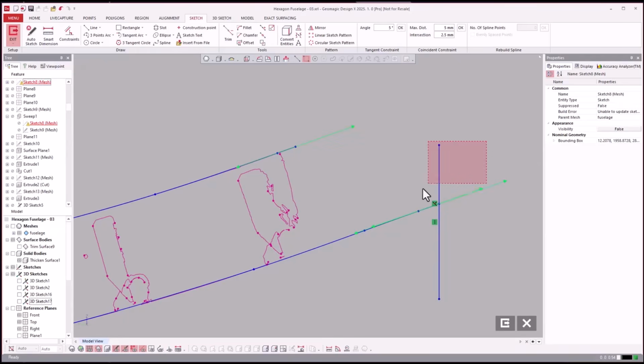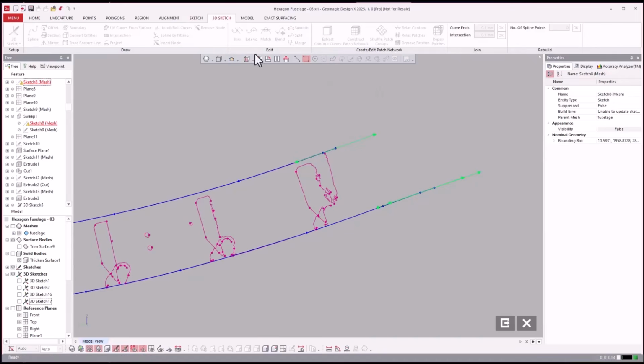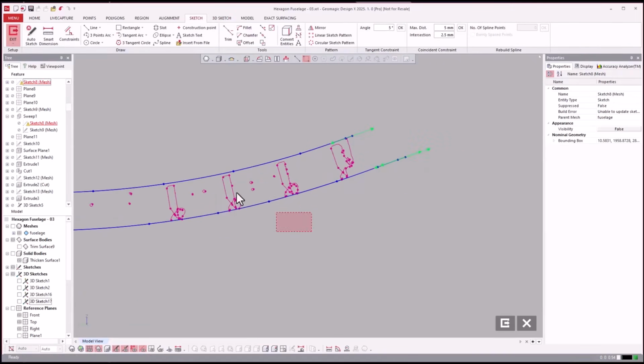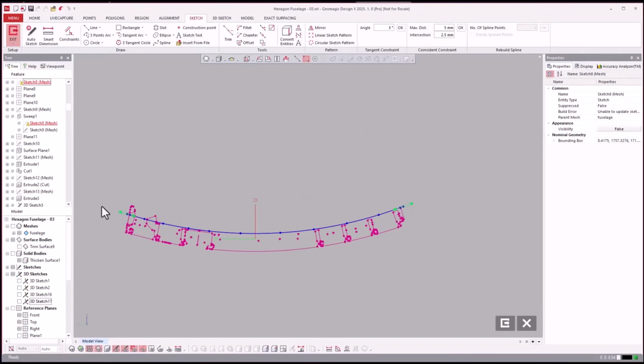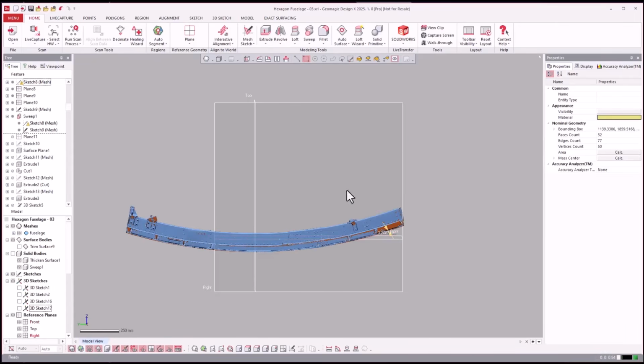So that's another method that you can do with splines. And now there was something else associated with those that I was thinking to bring up, but maybe it'll come up later. But the idea here is that I turned off the fitting to create this, and then we just drew a nice, beautiful spline through there that's going to be the guide curve for this.